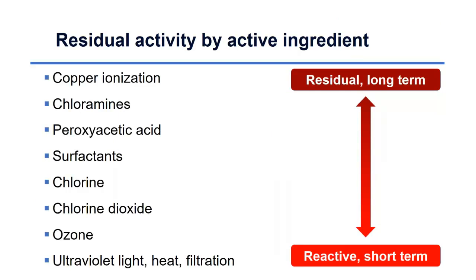And so getting here to the end, you might be asking yourself, okay, you've said how to design it, but I really want to know which technology I should be using to get rid of the biofilm in my system. And I really can't tell you which one would work. We think that there are products that work really well when they are in gas form. Products like chlorine dioxide tend to work well as an immediate shock. But again, when you think about biofilm and how things accumulate throughout the irrigation system, the longer the contact time, the longer the residual, the better it will be on cleaning throughout the system.